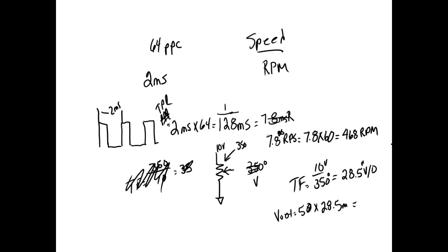So if we get the data sheets on the sensors and look at the input voltage, we can take that input voltage and get the maximum output or the range of the sensor, then we can calculate what we get in. And then when I bring that into my control circuit, that voltage or that current means something to my control circuit.